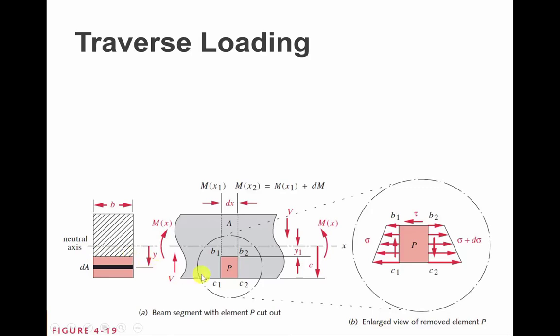That's what I'm interested in understanding. I know that there needs to be some shear stress, and what we're going to do is derive what that ought to be based off of what we understand is happening within the part. Okay? So a couple things to note. There's no shear stress on this bottom face. There's no internal stresses on the outside of the part.